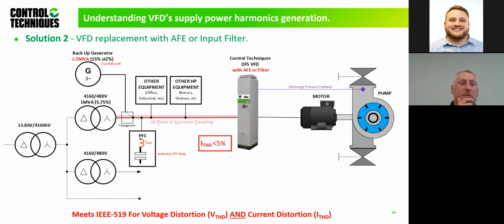It only takes something to come in and it takes it away. But the overall impact on the system is minimal now. It's less than 5% THD current harmonics for that Table 2 on the 519. But again, if you're operating around 4 to 6% VTHD, voltage harmonic distortion, you should be good. I'd be very surprised if you have any impact on other equipment.